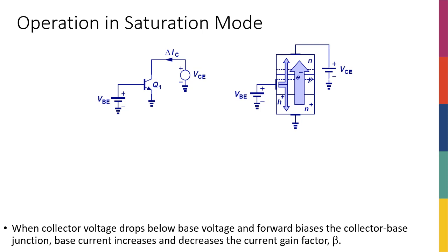So up to now, whatever we have discussed about bipolar transistors was about them being biased in the active mode, or the linear region, the active region. We said the condition for the active mode of operation was that VBE is greater than 0 and VBC is less than 0. Meaning the PN junction between base and emitter is forward biased, and the base-collector junction is reverse biased.